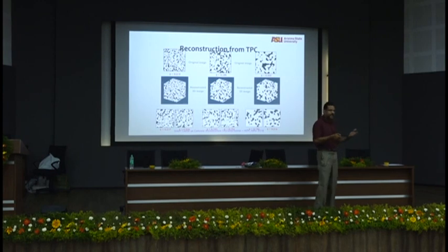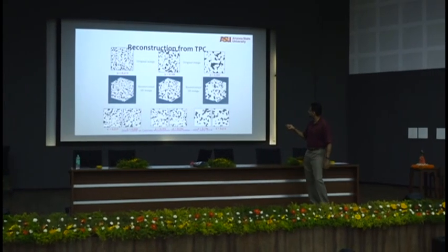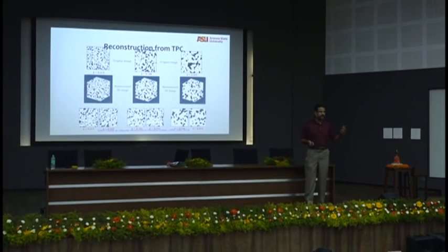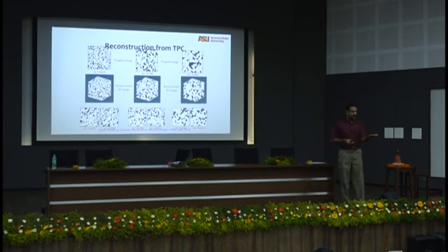Same idea here. So you take an image, use that correlation function and do some more manipulations, and then for the same image, what I'm telling the software is, here is my image, give me another 300 images where the porosity is very similar, the specific surface area is very similar, the pore size distribution is very similar, but the pore orientation is different. Is that not what you have when you take a piece of concrete and cut it into different layers and see?